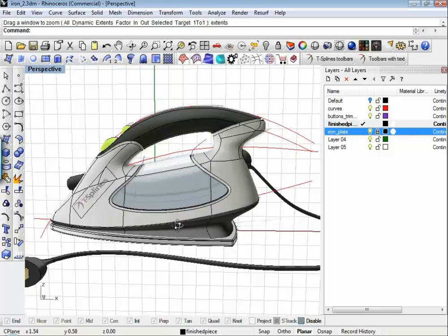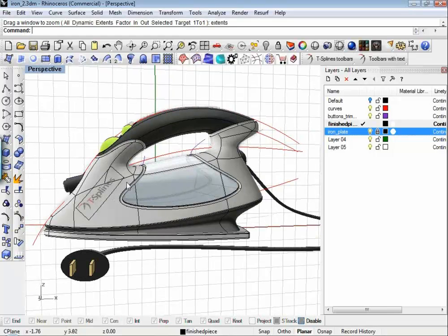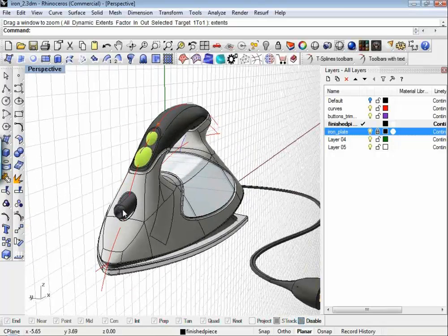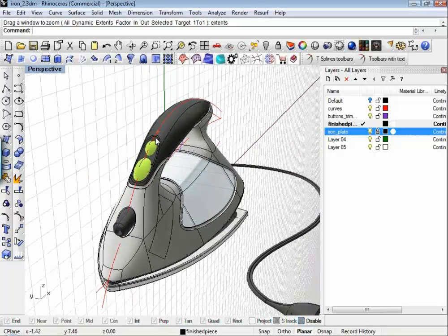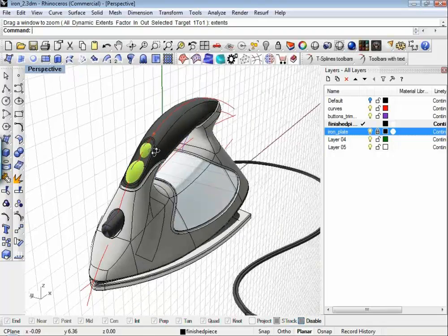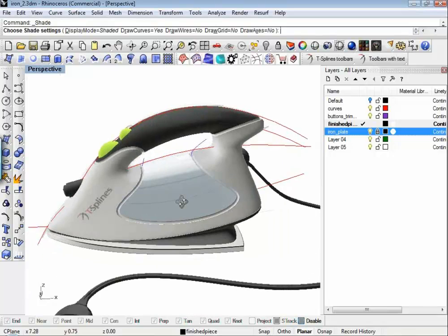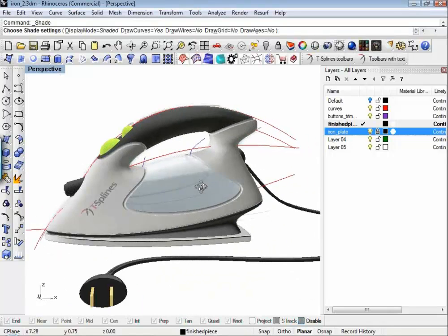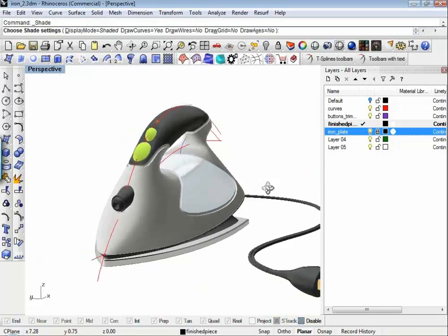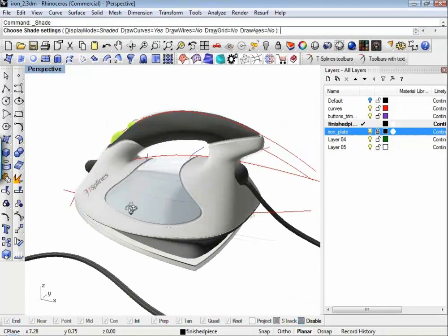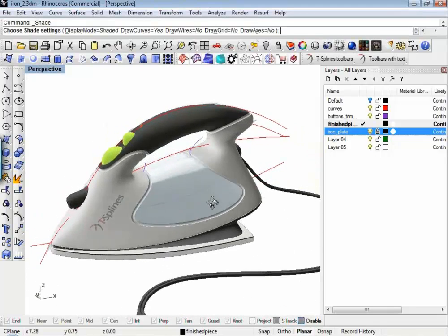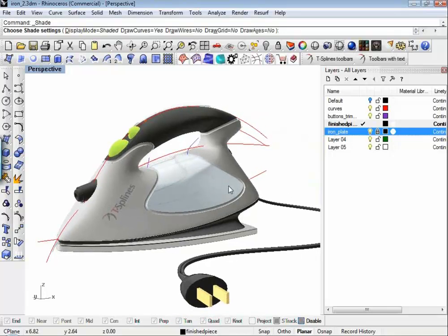Bring up my plate again. All I did was project curves onto this, Boolean this out, separate this. You know, I Booleaned out a sphere here, Booleaned out a single plane here, added all that stuff, and T-splines base surface, Rhino detailing, a little bit of Oxpecker shader, and you're done. And here we are 39 minutes later with a finished product.